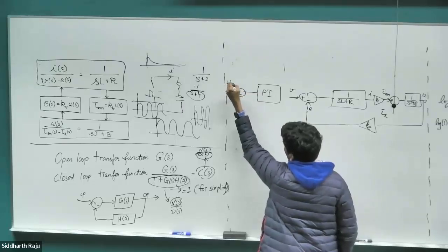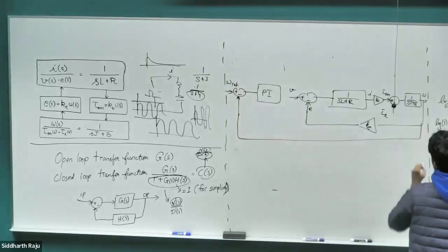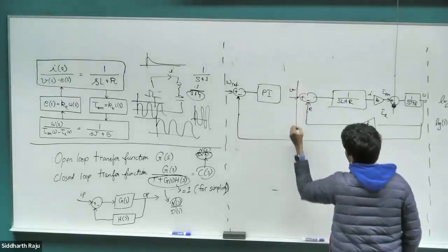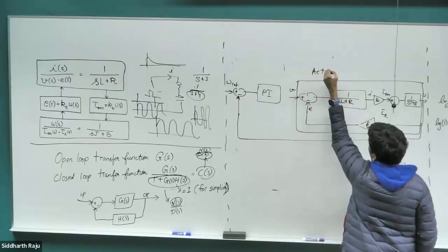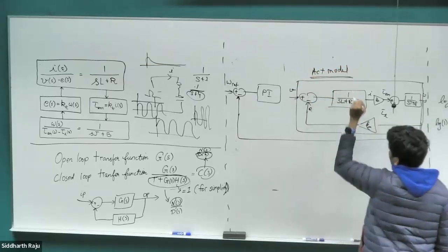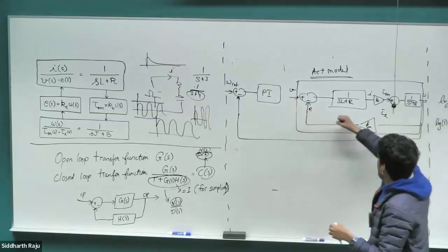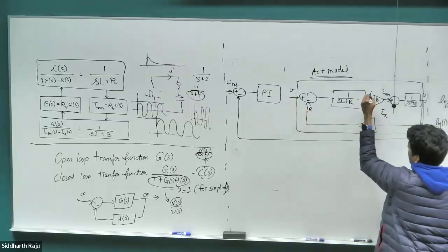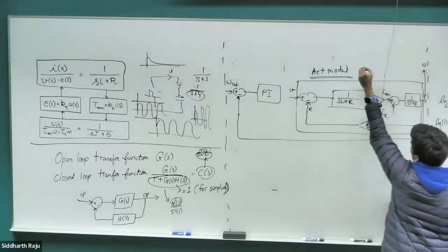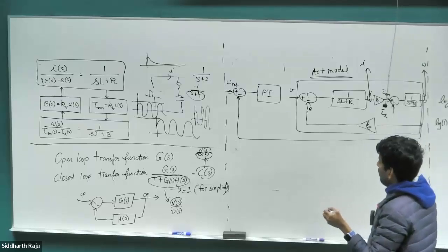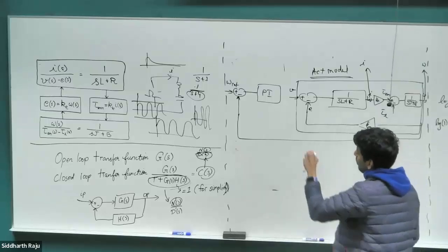And I want the speed to be some reference value. And I'm going to look at what the current speed is coming from the motor. So this whole thing is the actual motor, right? This is not the control system or anything. This is the actual motor that we are modeling mathematically. But in the real world, this will all be the actual physical motor that you hold. The only variable you can control is the voltage. You can measure the current in the motor by putting some kind of current sensor. So this information is available to you. The speed again is available to you. You can put some kind of speed sensor, some kind of encoder, to get the speed signal as well. Speed and position signals, all of those are available to you. And the only thing you can control is your voltage.